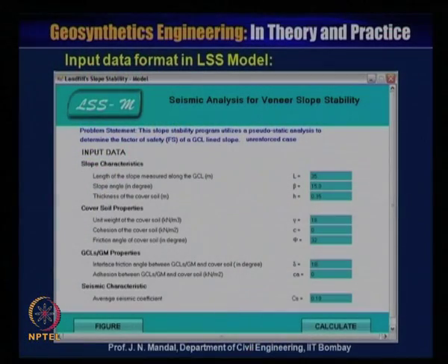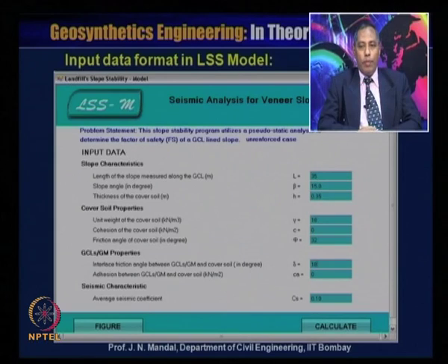So, here is the seismic analysis for landfill slope stability. In this problem statement, the slope stability program is utilized in a pseudostatic analysis to determine the factor of safety of a geosynthetic clay liner slope, and this is an unreinforced case.